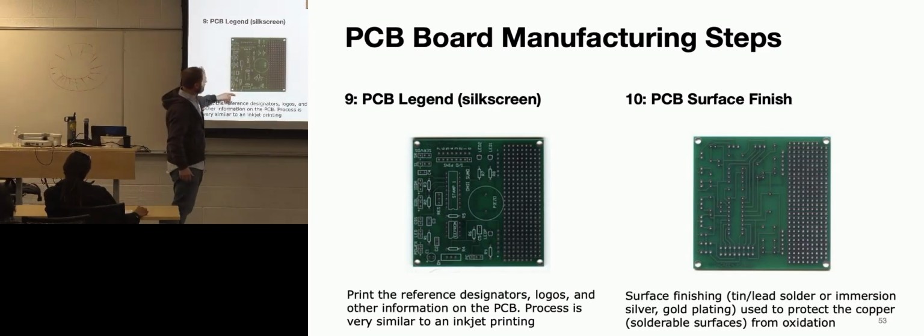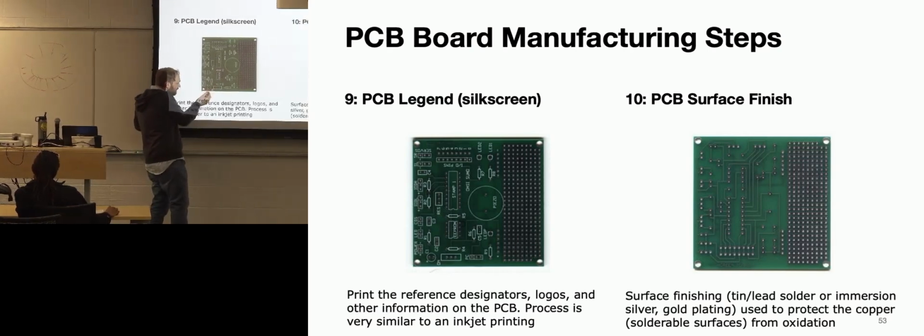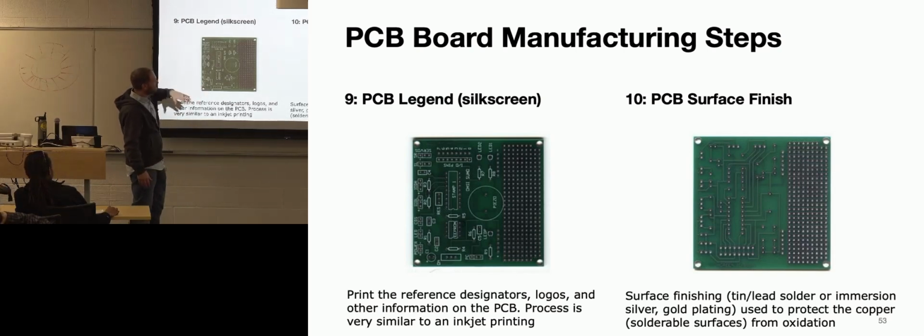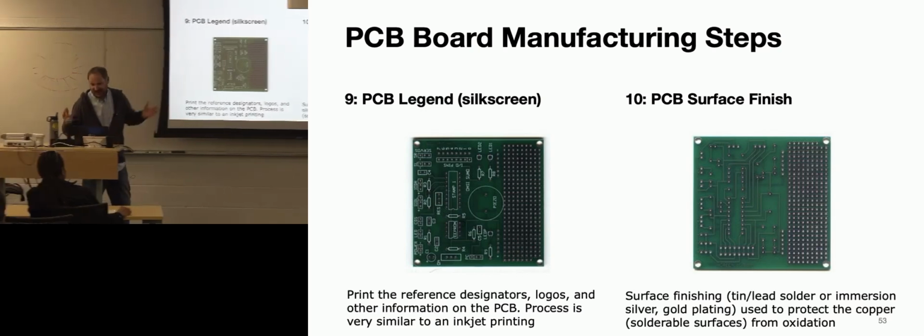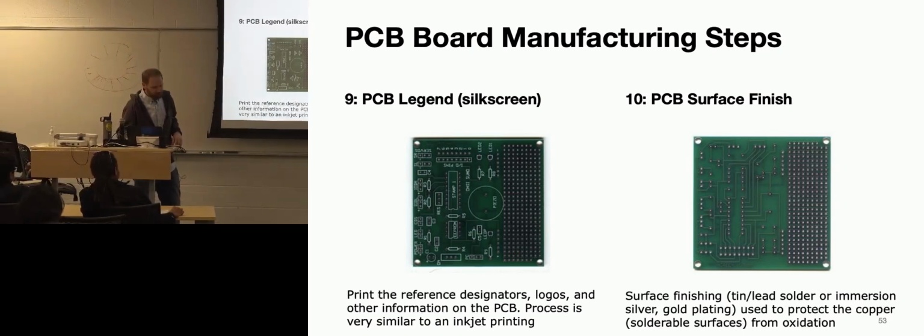But you get to go and put silk screen on there, so take a little time. It's just you and some good music and CAD, pushing polygons around, and you're putting silk screen next to your component. There are some standards you can use, basically trying to align them all in the same direction, to make it easy for yourself. Now it's cheap, you can get silk screen on top and bottom. There was a time when that was actually an extra cost.